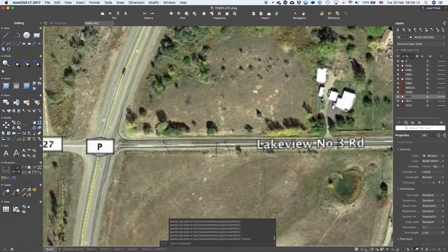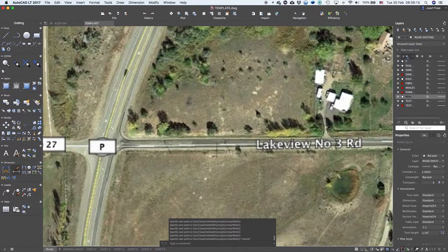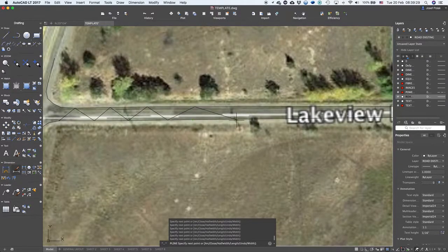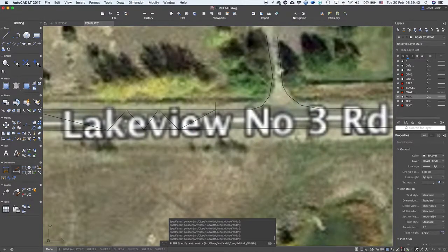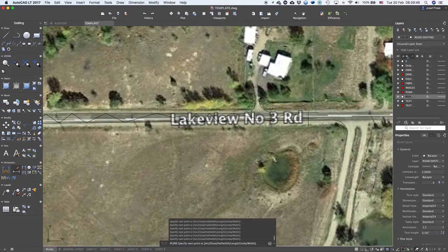Okay, so what I do next is I need to draw a center line. So how I do it is I create another P line which connects both road edges as like a snake line. If it's straight line, I can use like a longer distances. If it's bended, I need to do the triangles smaller so I can copy the direction of the road, right?